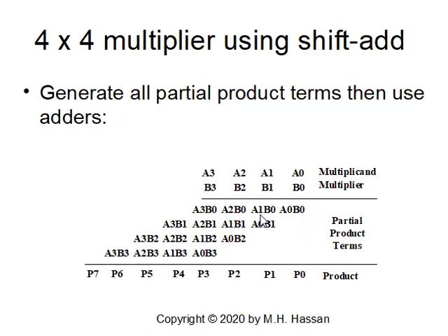Now we would like to add A1, B0 with A0, B1. It means we are adding P10 with P01. To do the addition, we can use a half adder, or we can use a full adder with 0 carry in. If we use a full adder, this will definitely generate a carry. The carry is to be added with the partial product terms P20, P11, and P02. To do that, we would definitely need 2 full adders.